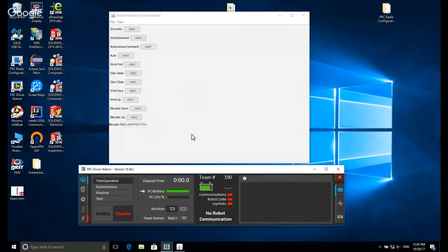I'm still a bit confused on how it's used. Is it the red thing right here? No, the potentiometer is the red thing right here. It's contained in that housing. What PID does is this sensor returns a voltage between 0 volts and 5 volts. And what we do with that is we say, if we get a value from the sensor of like half a volt, that means we want to run the motor at a certain power. So that's the P of PID. It's just saying when we have this value, we're going to run the motor at this value.